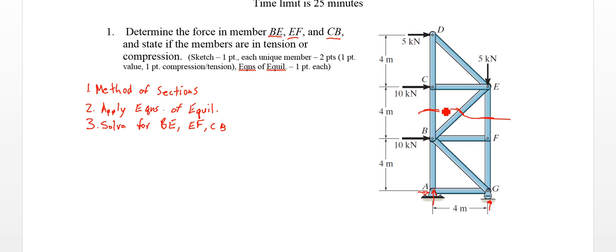In that truss. So looking at our truss here, I've already shown where I'm going to section it, so I'm going to cut through here, and I'll draw another sketch just of the section I'm going to leave here. We could either do the top or the bottom. If I do the bottom, I need to solve these reaction loads, what those reactions are. So that's 3 unknowns. I'd need to do 3 equilibrium equations just to get that part, and then I could go about solving this. If I take the top half, I already have these external loads, so I'm going to pick to do the top half of this.